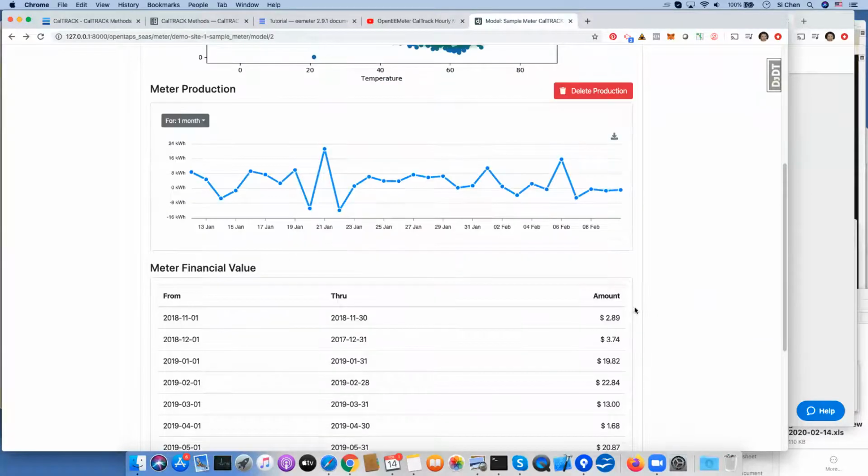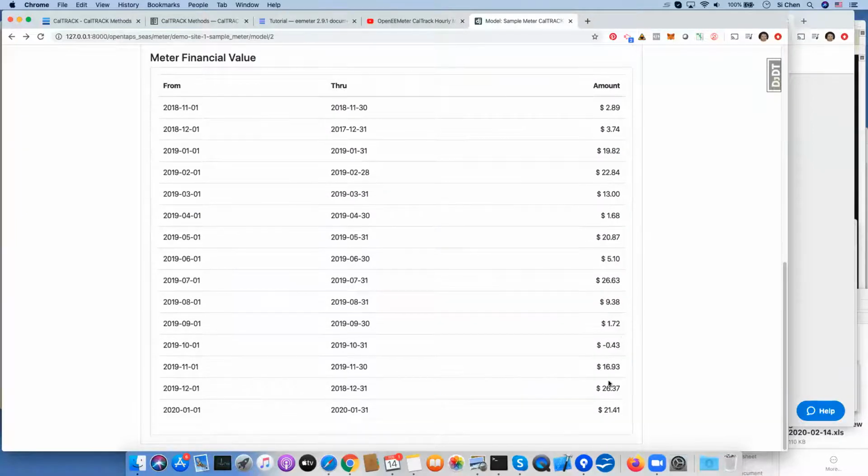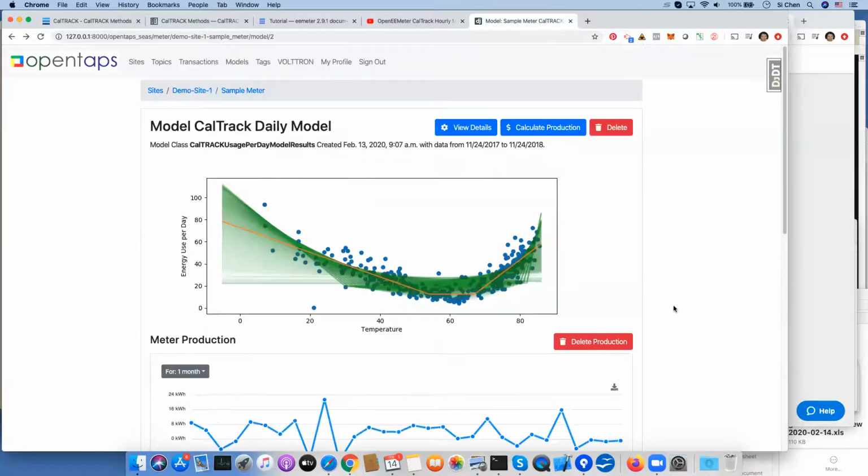And then from there, we're able to use utility rates to calculate the value of those energy savings over time. So that's what we do with it. And I thought this was kind of cool because you're all working with a lot of building level data from the BAS system and from other places. And what this does is it allows you to check whether different measures are actually saving energy against real utility data, which could be in short intervals, and real weather data. So you could tie in the different measures and see what their actual effect was.